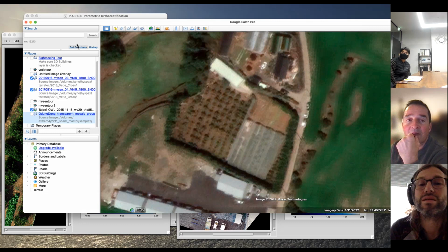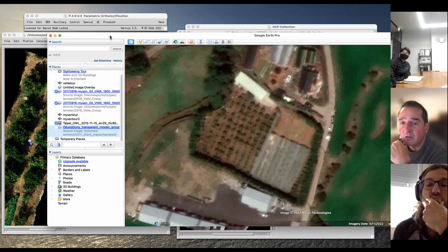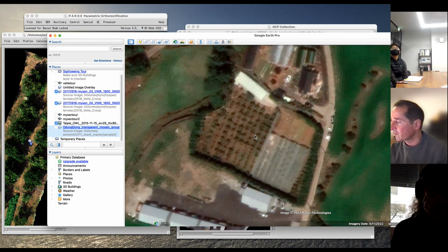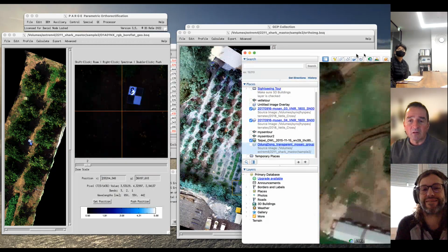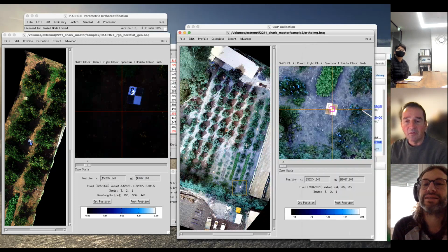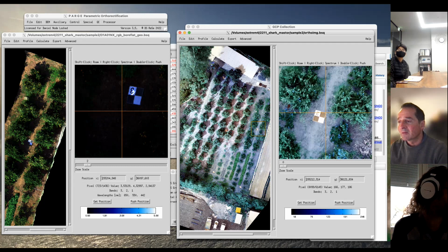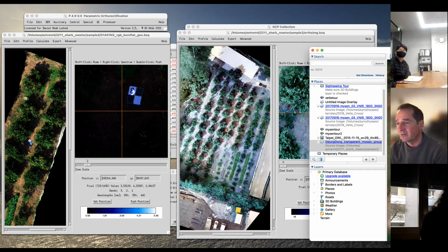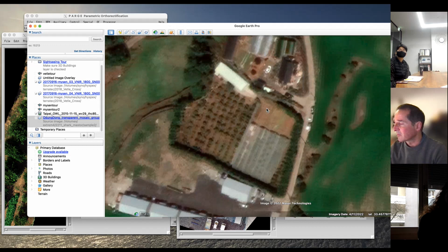Another reason behind that could be a coordinate conversion problem, such that a coordinate conversion is somehow squeezing or doing a distortion in the data. So in short, based on this data, I don't see a way to get a better accuracy. Using Google Earth directly is too coarse, as you see. So you cannot use Google Earth directly for this georeferencing.